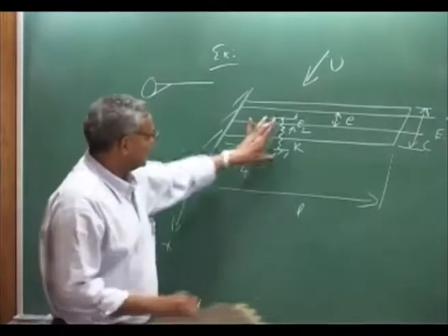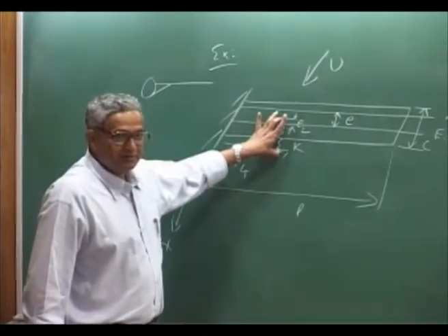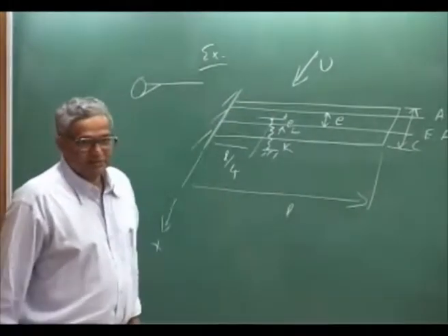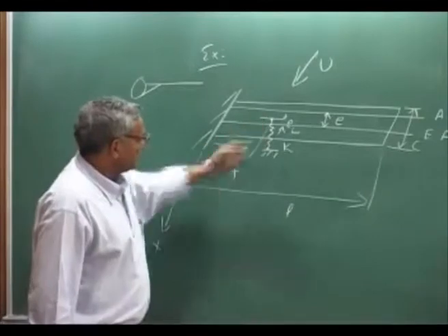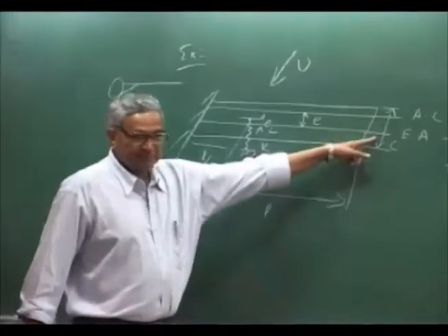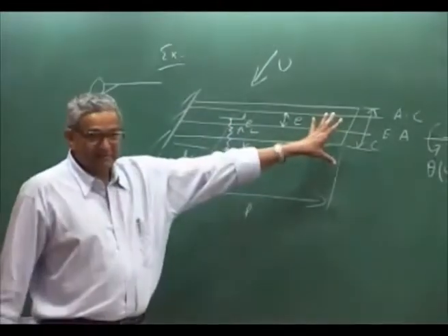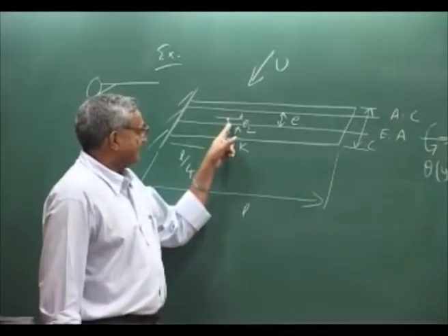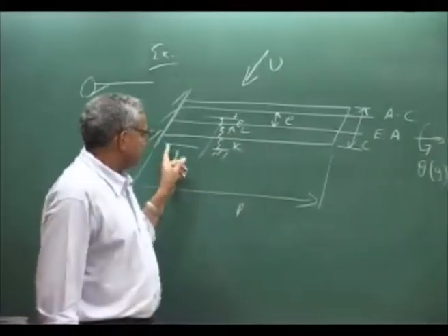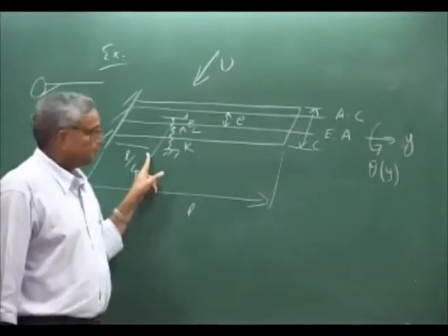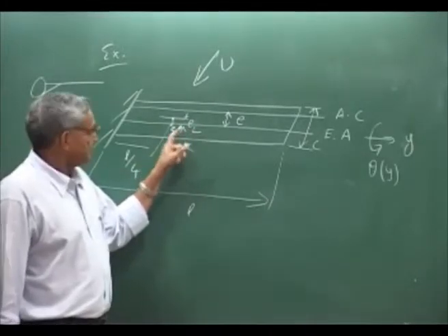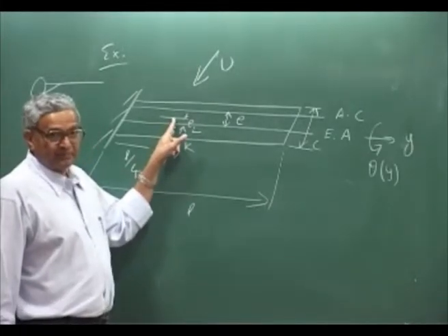Now the spring is going to deform depending on my twisting. The twisting will be because the wing twists, because this is a straight wing. Now what happens? This will be theta at L over 4 by the offset EL. That will be the deflection at this point.